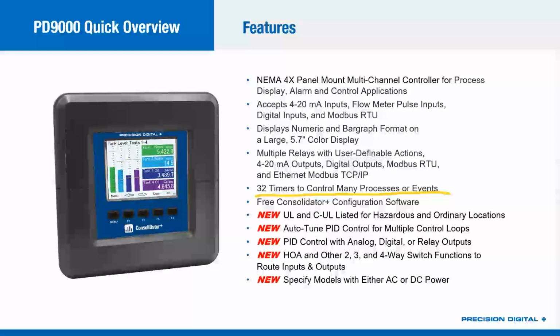Now, that programming can take you a while if you use the front panel push buttons, of course. Even just typing in, I want "tank 1 water" to be my tag, can take you a bit of time. So we do have free Consolidator Plus configuration software available. You just connect this up via USB, download the software off our website, and you start programming.